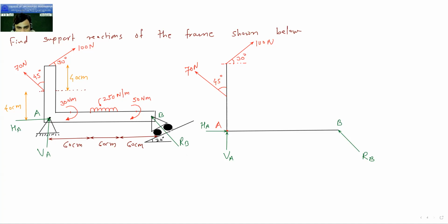Okay, this angle is 90 degree always. So I have already told you that if the angle between these two lines is 20 degree, here is 90 degree angle between this surface and RB. Now if I take a vertical line from here, this vertical line will make the angle of 90 degree with this horizontal. So if this angle is 20 degree, this angle will also be 20 degree. So here I can write this angle with vertical of RB, it is 20 degree. How does it come? Angle between the lines is angle between their normals or tangents. This is the theorem. Angle between the lines is angle between their tangents or normals.